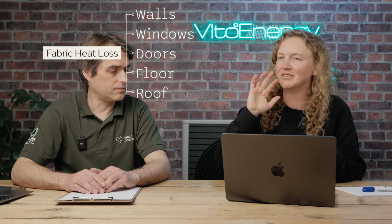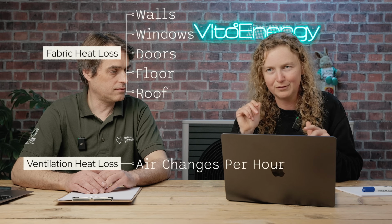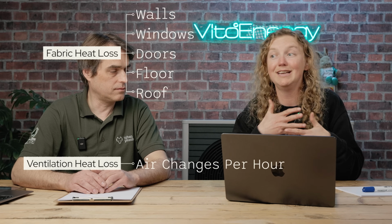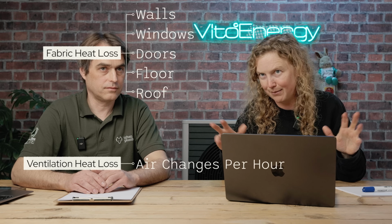Exactly. Okay, so if you've got the same size houses and same design temperature, same delta T, do they have the same heat loss? Absolutely not. So maybe to understand that, buildings lose heat in two ways. Either through the fabric, so conduction heat loss through the fabric. That means heat loss through the windows, walls, floor, roof. And then also infiltration or ventilation heat loss, which is heat loss from the air literally escaping through little gaps in the fabric. So hot air leaks out, cold air leaks in, and that's our ventilation or infiltration heat loss.